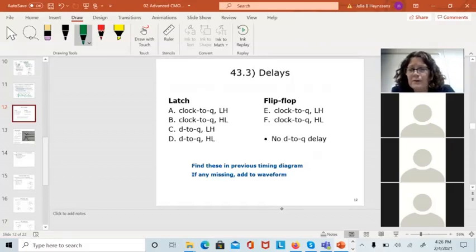There are delays through all these circuits. And this is what we're going to look at in lab 2, timing delays. With our timing delays, what we're going to find is it takes a finite amount of time, even through an inverter, for the output to change once the input changes. And you can imagine with a more complex circuit, like a flip-flop or a latch, where I have multiple NAND gates and NOR gates and delay lines and things like that, the delays are going to get bigger.